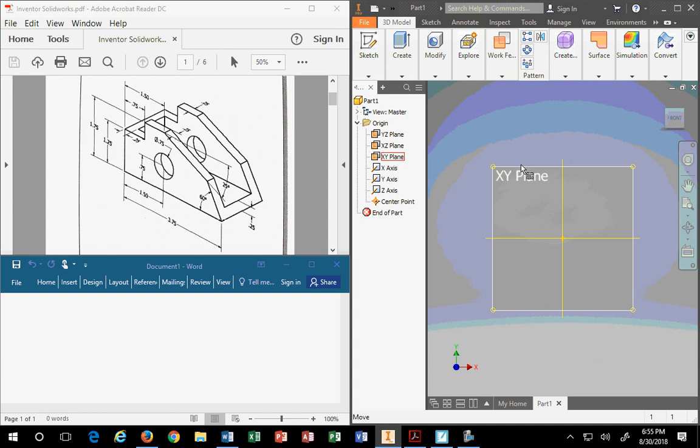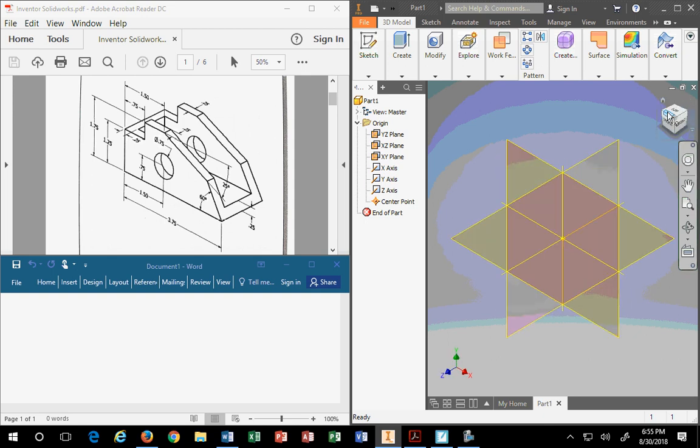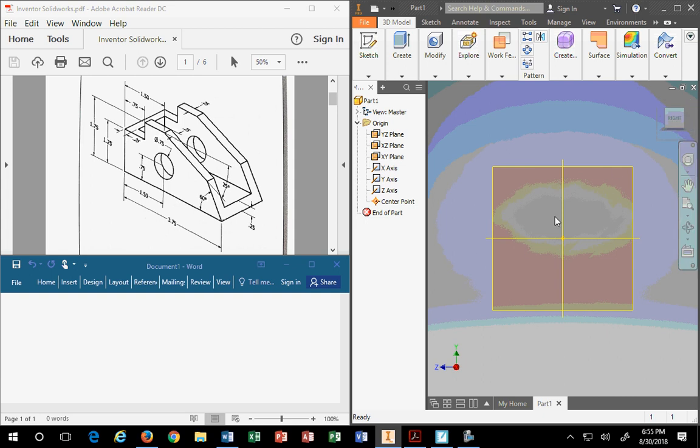They use the more generic geometric terminology of XY plane, but you can put next to it that it perceives the XY plane as the front of the object. Because over here in the icon, in the cube, they use the word front. So if I go home again, and then I click on the right side, it says right, and that's the YZ plane. So write that in your notes, the YZ plane. If you go home again, and you click on the top view, that is also known as the XZ plane.